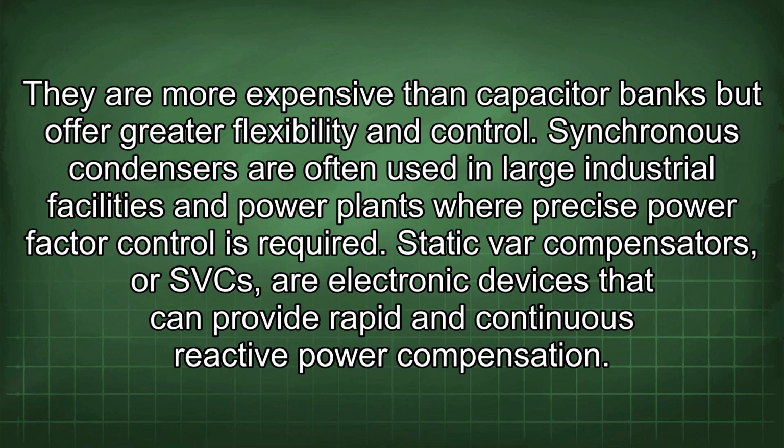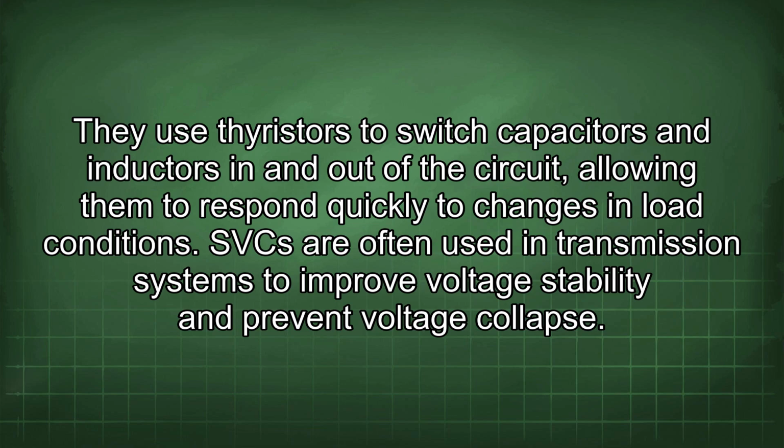Static var compensators, or SVCs, are electronic devices that can provide rapid and continuous reactive power compensation. They use thyristors to switch capacitors and inductors in and out of the circuit, allowing them to respond quickly to changes in load conditions. SVCs are often used in transmission systems to improve voltage stability and prevent voltage collapse.